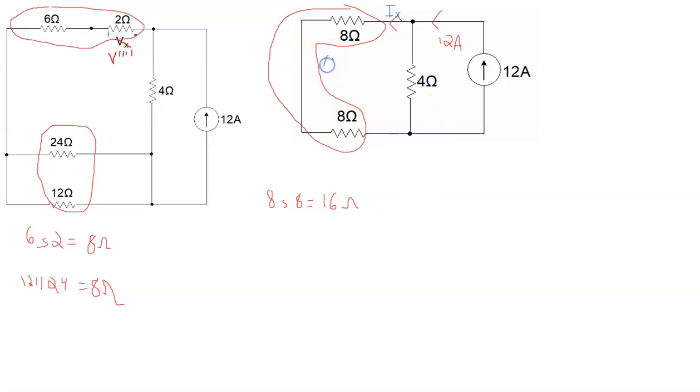And so remember now that that 16 ohms right here is our X, and REQ then will be RT in this case, which is 4 ohms in parallel with 8 ohms. And we have then 4 times 8 over 4 plus 8, which is 12.